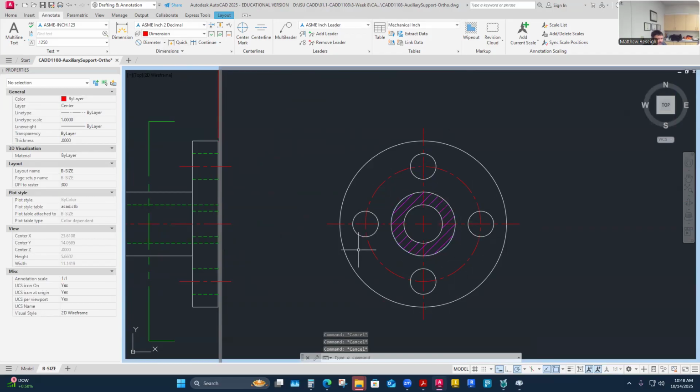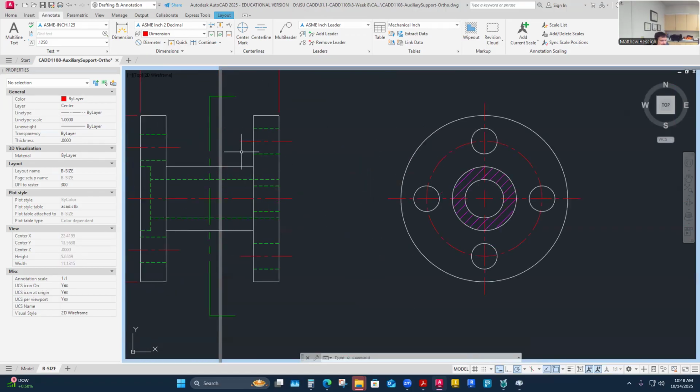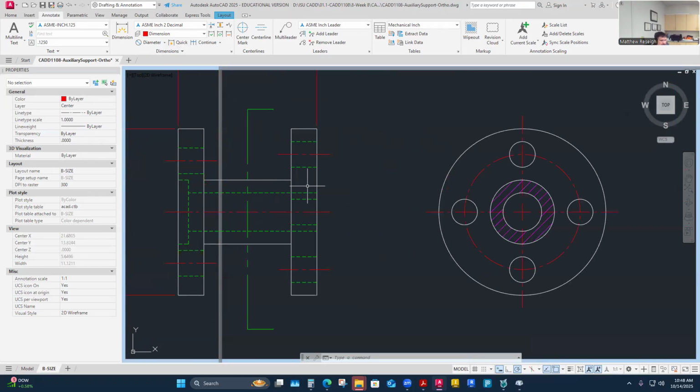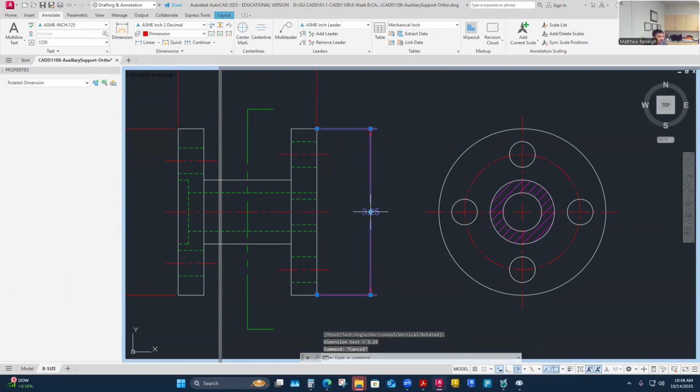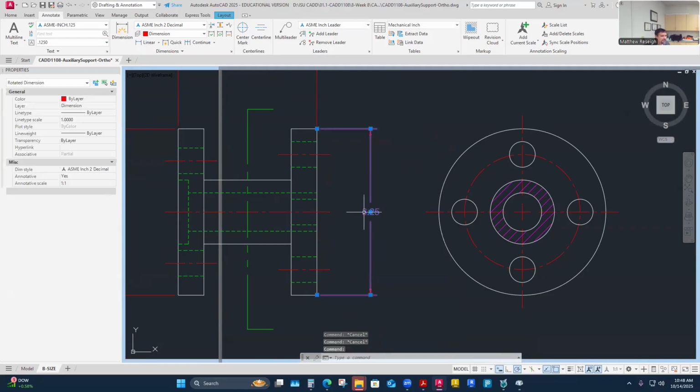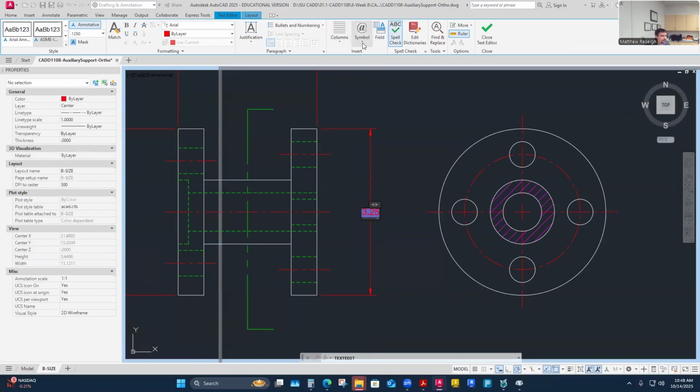So here's the outer plate. Great. I could throw the diameter here. That would be a good dimension. The better dimension is definitely coming off the rectangular view right here where it's pulled from. So I'm going to use a linear dimension for the diameter right here as the preferred dimension of this plate. And then I've got to add a diameter symbol in front of it.